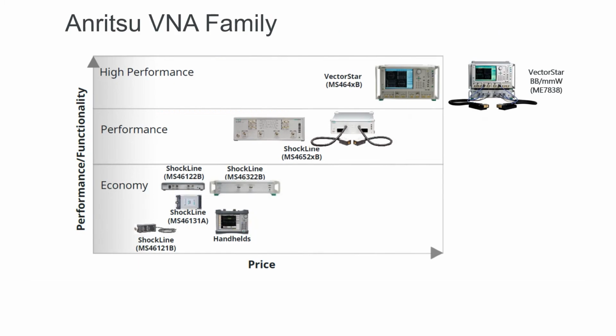Okay, continuing on with the VNA, which is really the measurement engine behind the measurements that Brian was talking about that are required to build up the model for the probe. We need a differential VNA. Of course, for the first 2 steps, it's an open and a short. That's a 2-port measurement. But we need the 4-port, obviously, to make the in-situ measurement. And then later on, when we're using the probe and de-embedding it, we're talking about differential measurements. So once again, we need a 4-port.